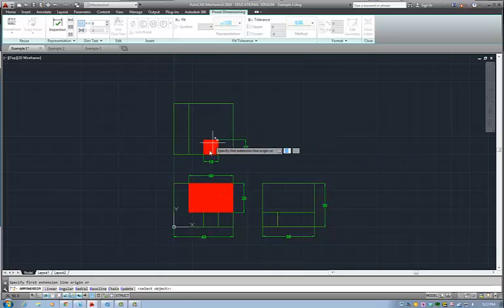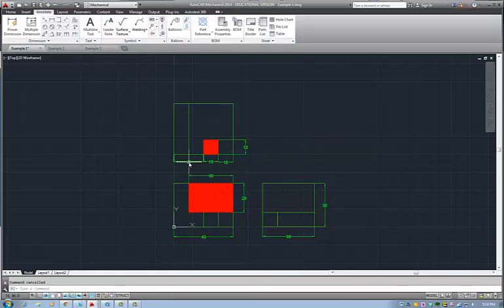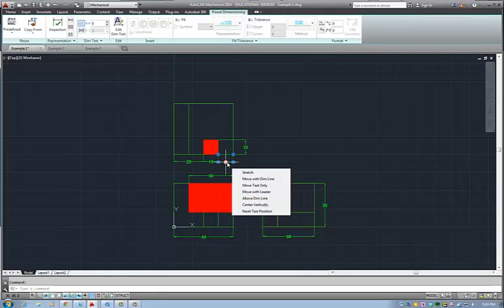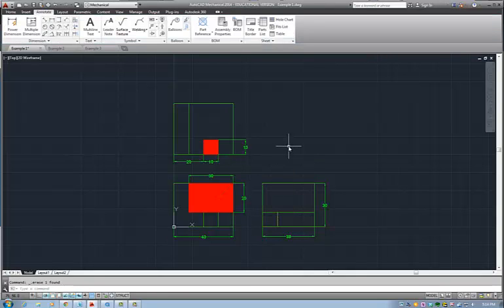But dimensioning the size, that's not enough. You also have to dimension the location. So in this case, you see this dimension 10. I will have to add either something from the left here, 20, or I will add a dimension from here to here. Having all three of them is wrong. So either delete 20 on the left or 10 on the right. So something like this. And I don't need another dimension because this one is really lying on this lower line. So I don't actually need that.